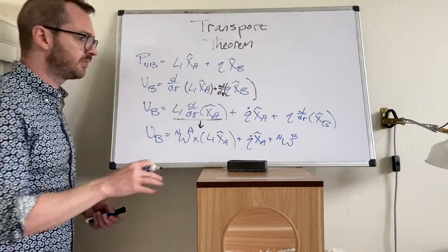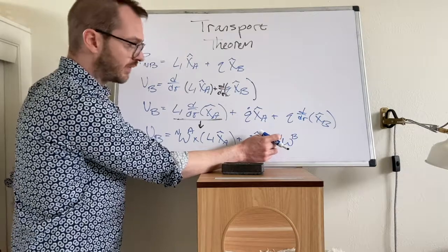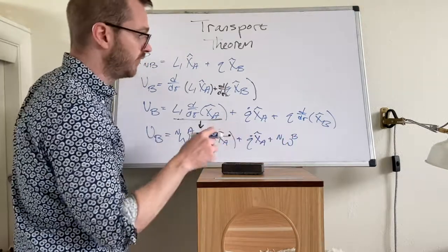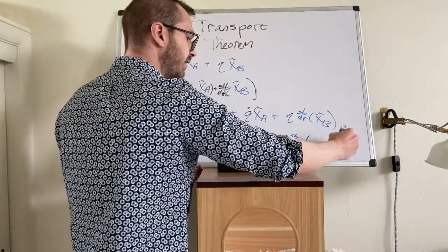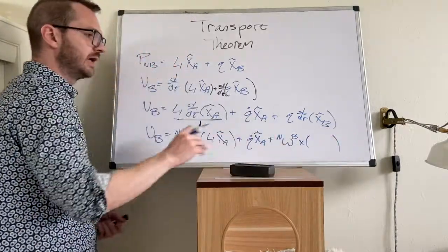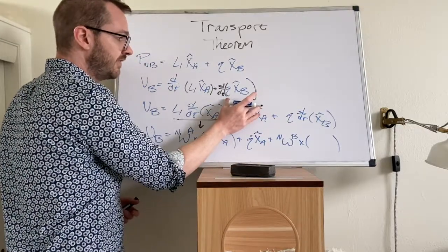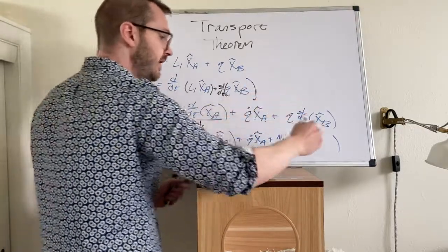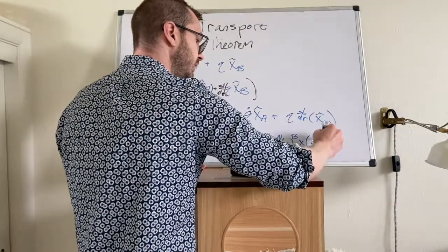When you apply transport theorem, it is the total angular velocity from the N frame all the way down to that rotating body frame. So it's omega N to B cross, and then we have to bring in a vector here. What do we bring in? Where did this come from? You're taking ddt of this position vector, take that and bring it down: Q x hat B.